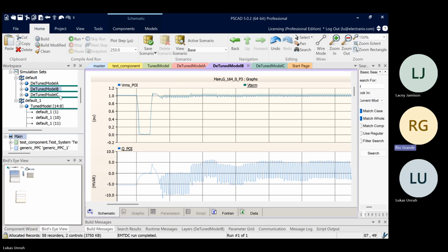And also the thresholds. People love to change the threshold for ride through, especially in ERCOT, right? Because in ERCOT, if I make the high voltage ride through threshold 1.4 per unit so that I'm never going to hit it, I'm going to have a beautiful, perfect ERCOT response: a perfect straight line down, maximum Q, active power 100% perfect. But that's not something you're going to want to change in the product, and it's definitely not going to get past the manufacturer. There are a lot of reasons not to change things unilaterally.